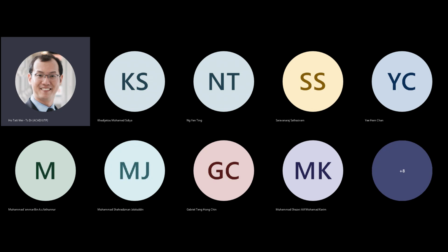And if you want to assess the fastest period at which I can synchronize all this computation, you need to look at the propagation delay through this block, this block, this block, and this combinational block.